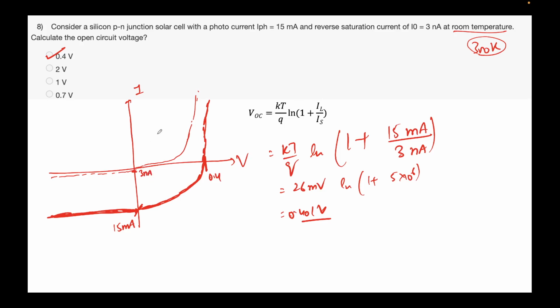So essentially a good way to see IV characteristics is to put current in log scale, because 6 orders of difference you will not be able to appreciate here, and this problem will become more prominent when we talk about the next sets of devices, the photodetectors. There, the change in order is 6 times at least. Such changes in magnitude are not perceptible to a good extent.